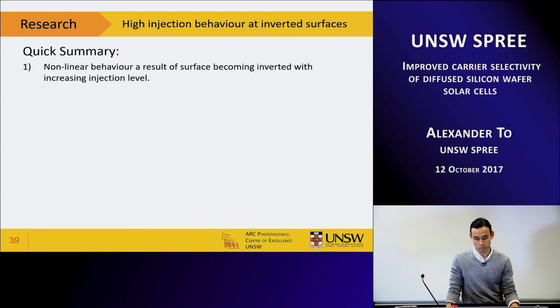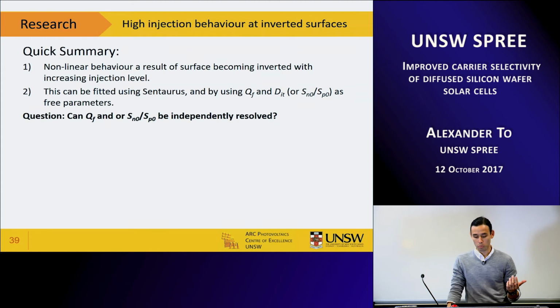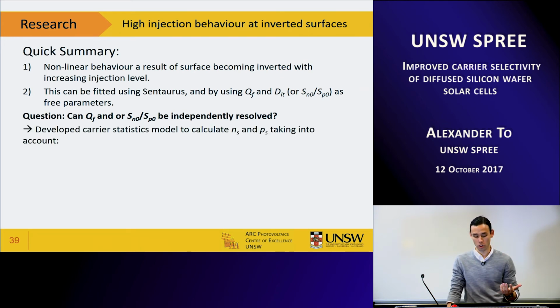So, quick summary: we showed that this nonlinear behavior is a result of the surface becoming inverted with increasing injection level, and that we can fit this in Centaurus. The question then was, this is a unique bend, so maybe we can start to fit and extract some parameters from these curves.